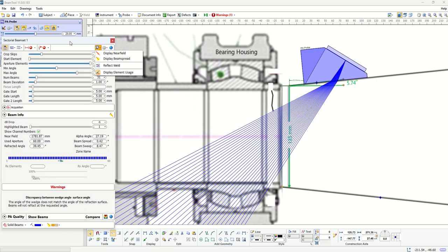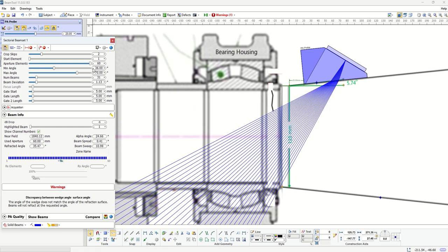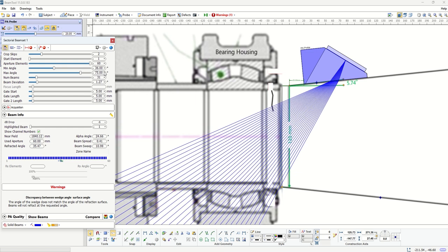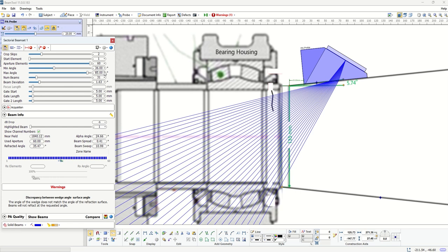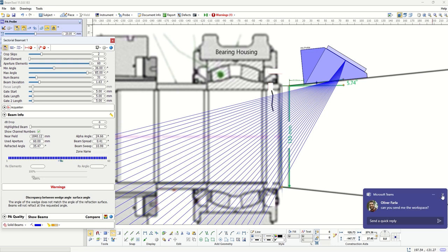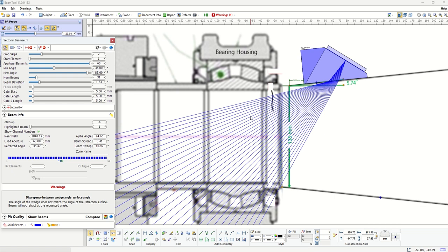Now I can set the range of angles. Let's say I need to start from somewhere like 36 millimeter and go up to cover this, let's say around 85 millimeter. And notice that here we only have a chance to hit this potential crack indirectly, so that's why we need to go to very high angles, although we know that in some cases they are not steered very properly or ideally.